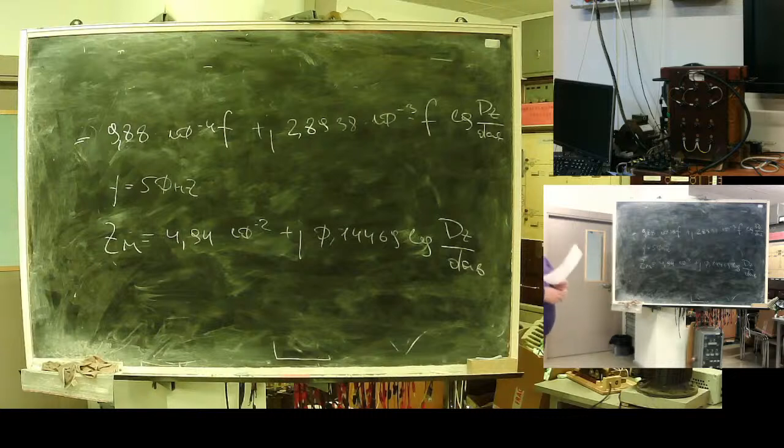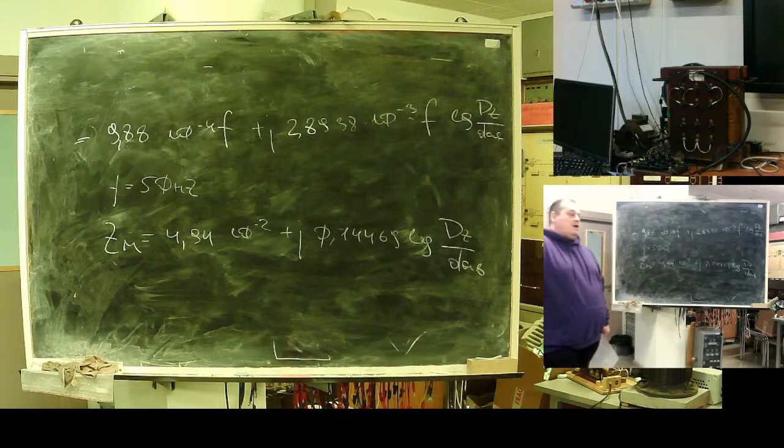Are the high voltage cables insulated or non-insulated? Super high voltage overhead lines, there is no reason to insulate them. Real insulated cables are used somewhere around 24 kilovolts, which is a reasonable upper voltage. For higher voltage, it's not profitable.